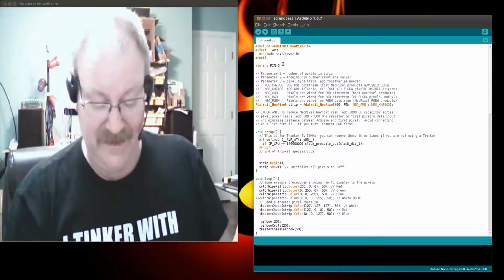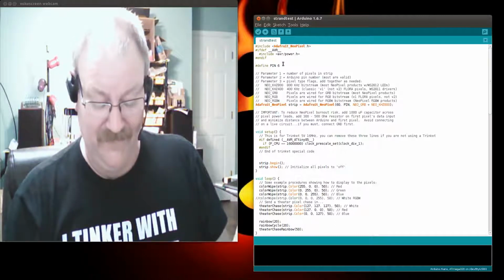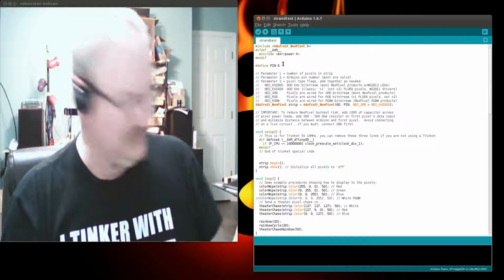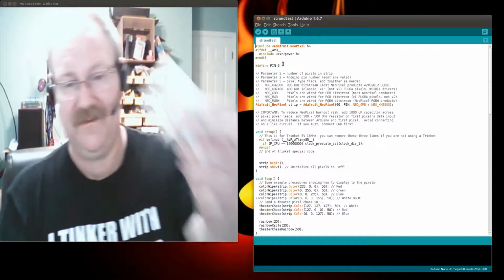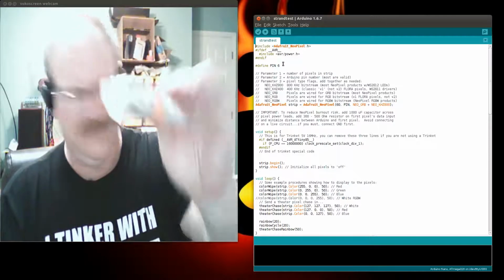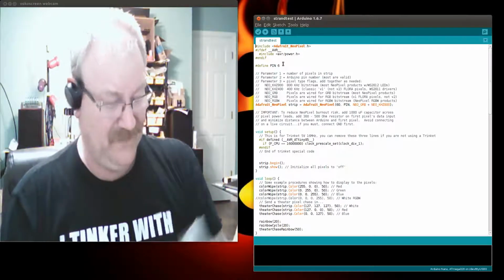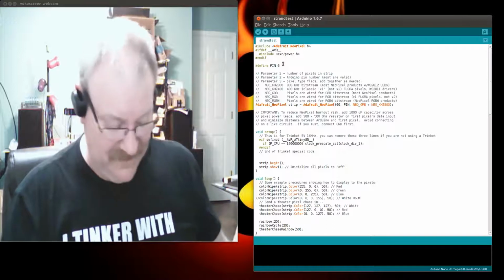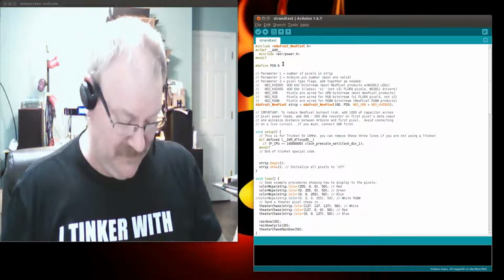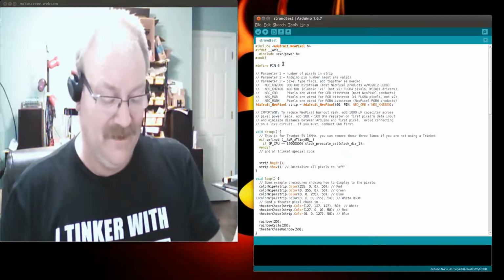That is a yellow, violet, brown, gold resistor. There should be a whole bunch of them in your kit. If you bought a kit, probably 20 something of them. And that's a bag of 1,000. I'm going to get one, and we're going to install this 470 ohm resistor on this board.